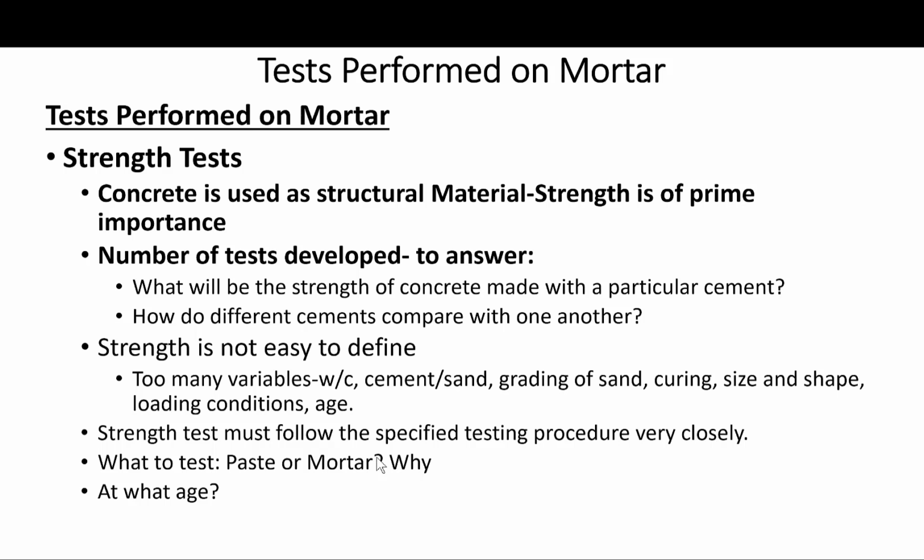It has also been found that cements that appear to be the same when tested neat may behave quite differently when used in mortar. So mortar tests provide a more reliable indication of cement quality when it comes to strength tests. The tests on neat pastes are now used only for research purposes. However, having decided to use mortar, the sand must be carefully specified as done by the ASTM standard. Again, be careful of what I said about the sand.